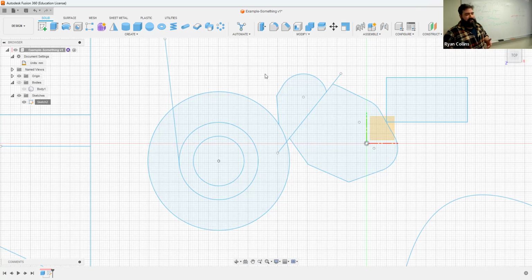Main thing is make a sketch, lines make lines, fit point splines make curved lines or amorphous lines, and you have your variety of circles and rectangles and triangles and anything in between. Constraints allow you to freehand some stuff and then lock it in place later or make changes with a dimension tool, things like that. But there's a lot to learn. I don't expect you to learn everything right off the bat, but that's a general walkthrough of the interface. So let's pause there and come back.